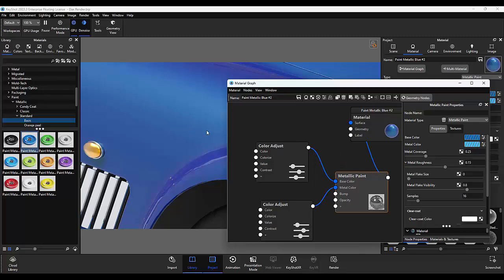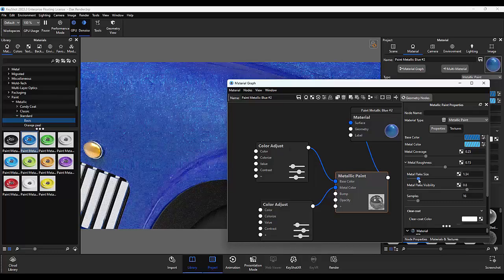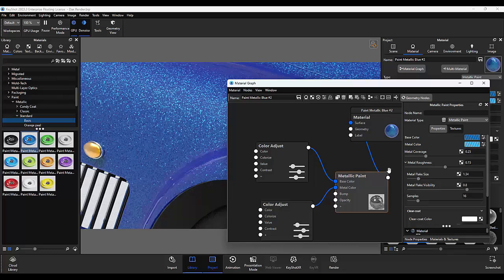At the moment it's not amazingly obvious how this is being adjusted, but these are what we refer to as flakes. At the moment the flake size is set to 0, which means it's just a solid colour underneath. However, if I increase the amount of flakes, or the flake size, you can see there are these little individual specks of the secondary colour, and that's what's giving our material the hue.